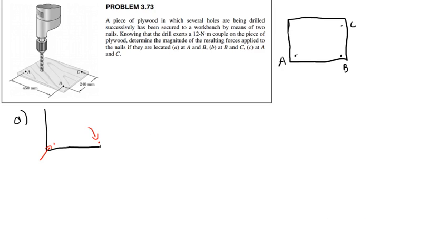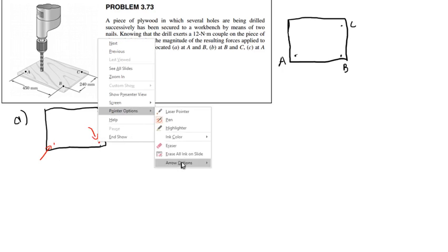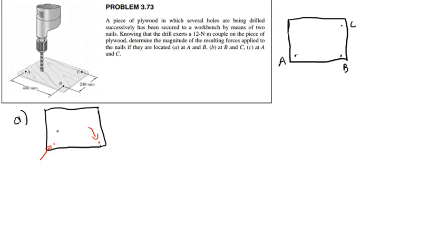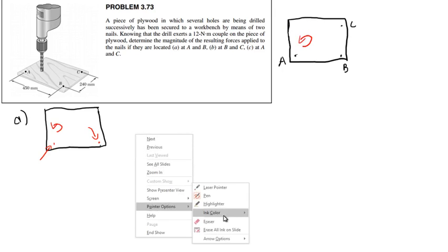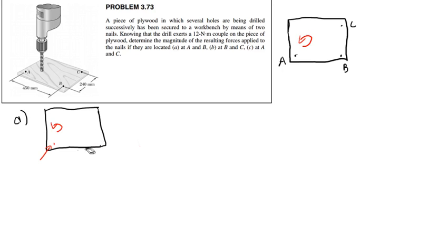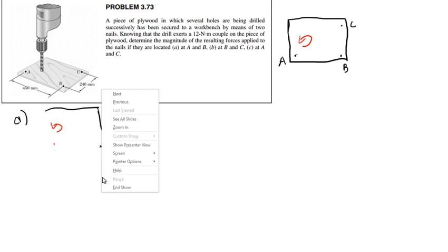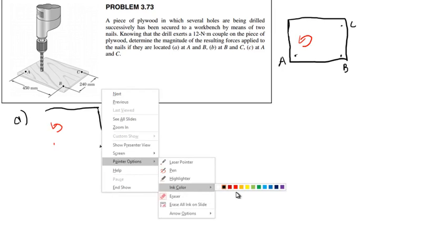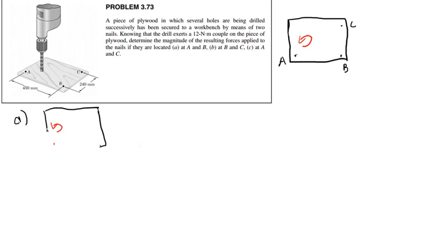Okay, so these forces as drawn are not going to work, simply because they are not equal and opposite. They are going to introduce some sort of translational force, which, since there's nothing to resist that translational force, the board's going to go flying through the air. This would not remain in static equilibrium. So what other options do we have? This isn't going to work. Instead, these forces must be equal and opposite. It keeps erasing my other lines. These forces must be equal and opposite.